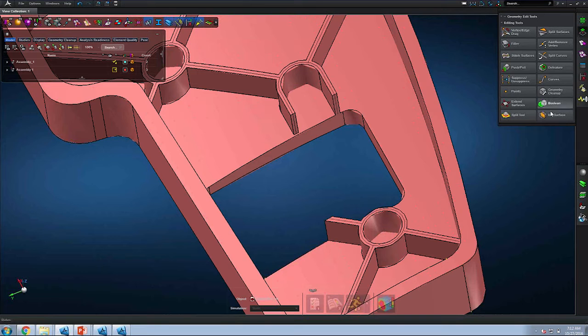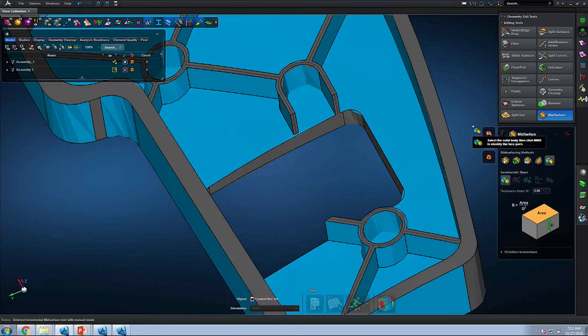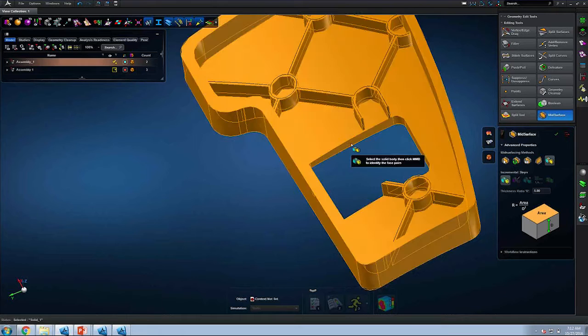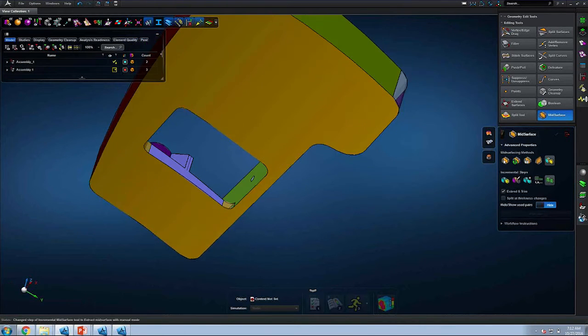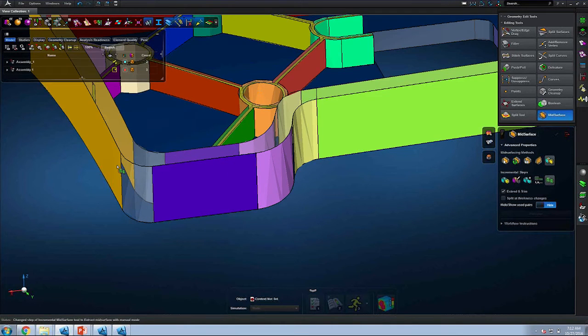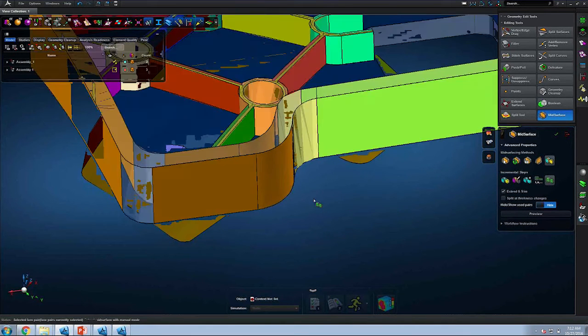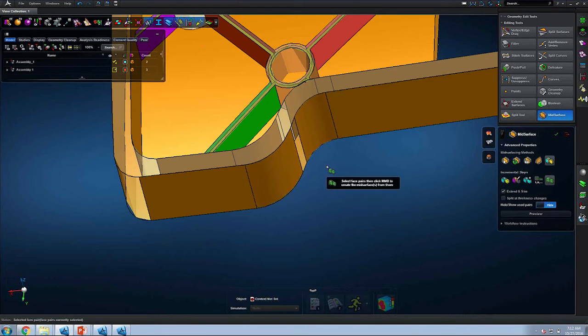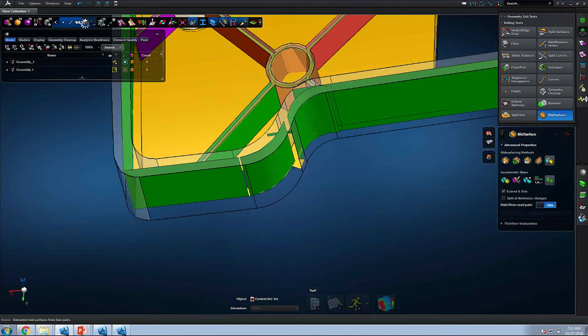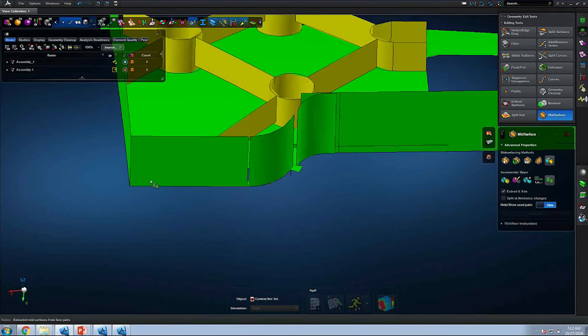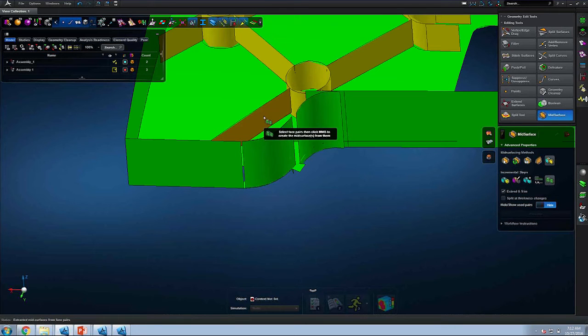So now let's go ahead and use an automatic method of extracting a mid-surface for this. I will really do no modifications to this. What I want to showcase is just how incomplete the mid-surface geometry can be when you first extract the geometry without any modification. And here in a moment you'll find the creation of this green mid-surface geometry. Let me go ahead and suppress the visibility of the solid. Here in green is what we actually extracted. What you see in yellow is something I created before this presentation.